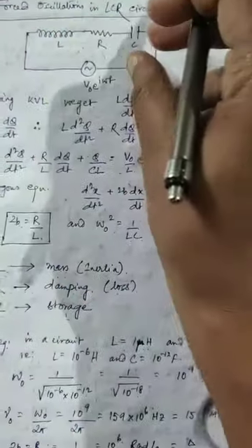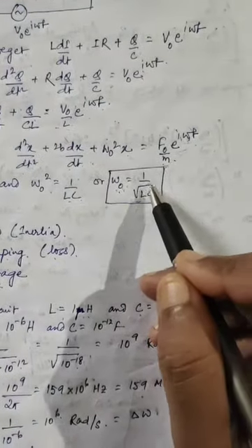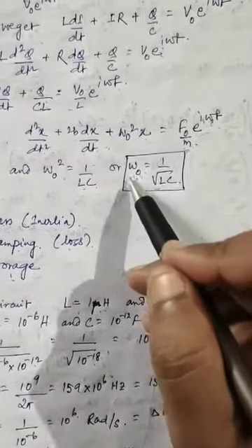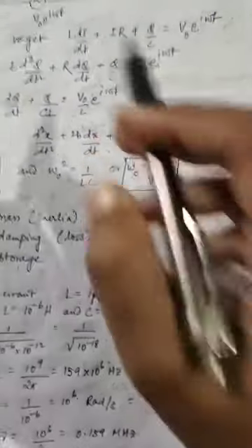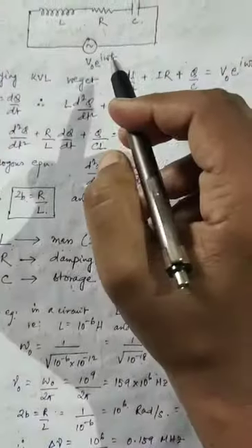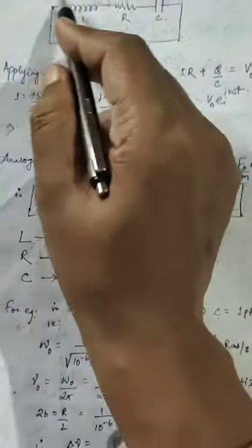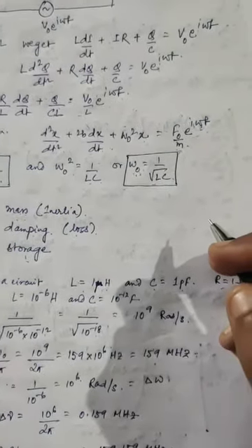But if I somehow change the inductor or the capacitor, that is, if I adjust the L and C value so that the omega naught value changes and matches with the frequency of this radio wave, then there will be resonance in this circuit and maximum power will be delivered, and your circuit will work. And this is how your radios work.